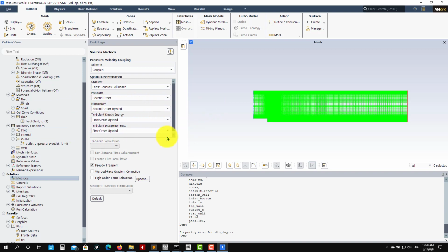And for the turbulence variables also, you can get it second order or first order, or even higher. There is no problem in first order. However, second-order accurate sometimes will give you a slower convergence rate. Okay, so here it's not a problem if you put first order. Remember, turbulence is diffusion, so somehow you will enhance diffusion, but feel free to play with second order and see the convergence rate. Solution shouldn't change a lot in this case. I will leave it the default proposed by Fluent, by the way.